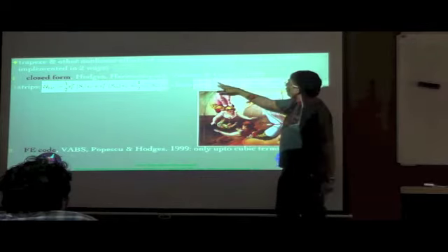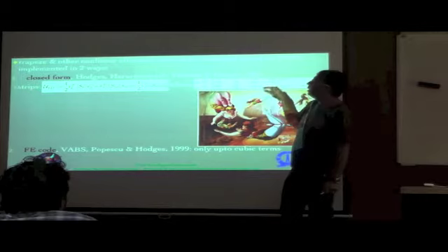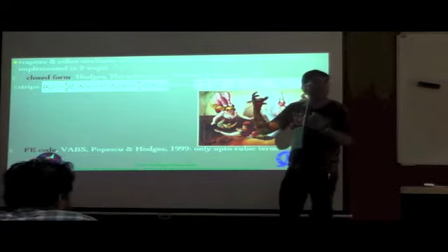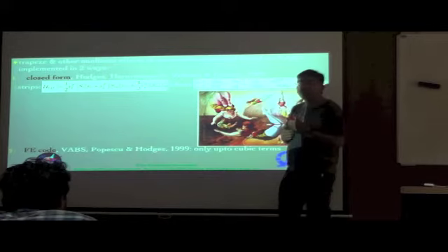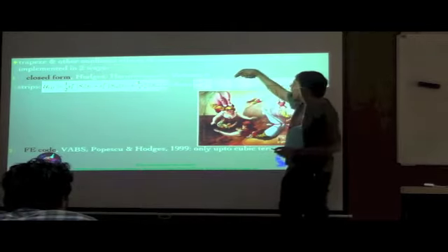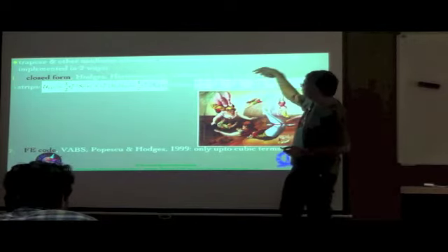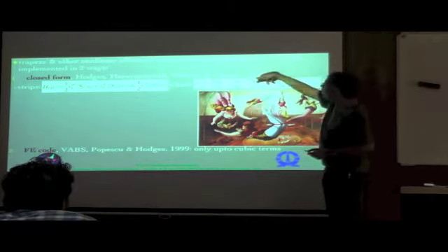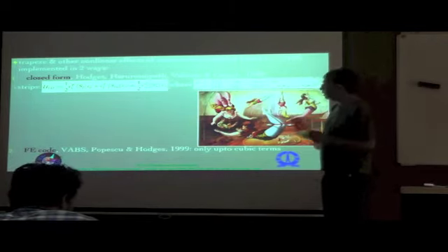So basically, you have the extensional strain, the twist per unit length, and the two bending curvatures, and all the elements of SL are constants. In other words, you have a linear cross-sectional theory. In other words, the relationship between axial force and gamma 11, the torque per unit length and the twist per unit length, and the bending moments and the bending curvature are all linear in such a situation.